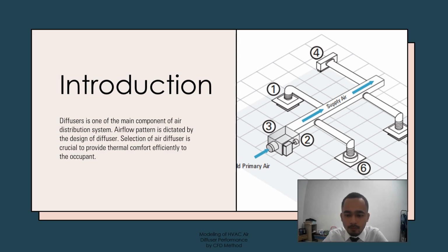But for my research or my study for this PSM, I am more focused towards the diffuser itself. Diffuser is one of the main components of an air distribution system. The airflow pattern is dictated by the design of the diffuser. Different design of diffuser produce different type of air projection. And we can say that selection of air diffuser is crucial to provide thermal comfort efficiently to the occupant.